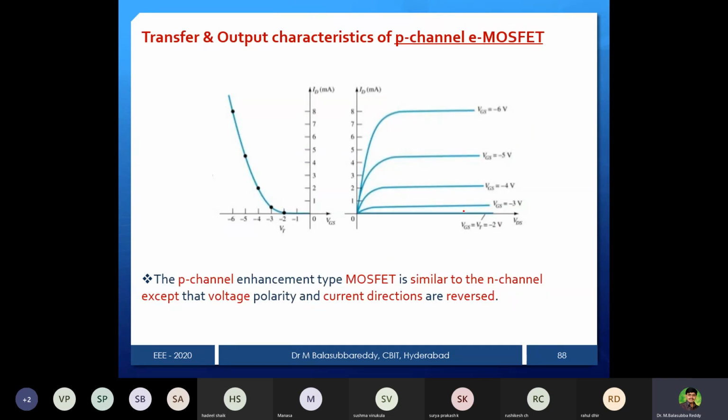And this is the case for the P channel enhancement. The only difference is the currents. What will happen is that VGS is negative because the directions change. So now it will be threshold, and after threshold it will develop on the negative side, and here you can see that VGS we can make negative in the case of a P channel. Earlier I showed the characteristics of an N channel enhancement, now it is a P channel enhancement.